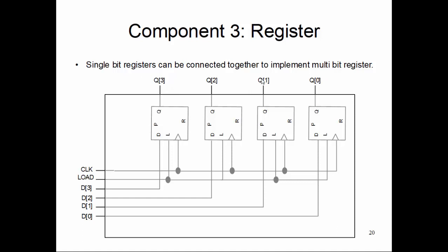So that's a general concept how these registers are built up from basic gates, right? So you can well imagine a 4-bit register has 4 1-bit registers. Each of the 1-bit registers has one D flip-flop and one 2x1 1-bit multiplexer.